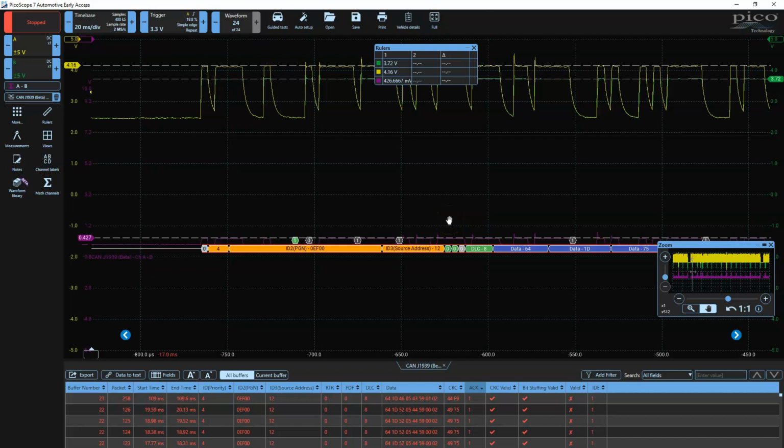Now, the device isn't the thing which has the failure mode. The failure is something related to wiring. What I've done here is I've inserted a resistance in series between CAN low and the fuel pump. So basically, at the stub, the point where the fuel pump would attach to the backbone, if you can imagine the connector, the terminal, I have corrosion on the terminal. In this case, it's such that it's not an open circuit, but it is high resistance.